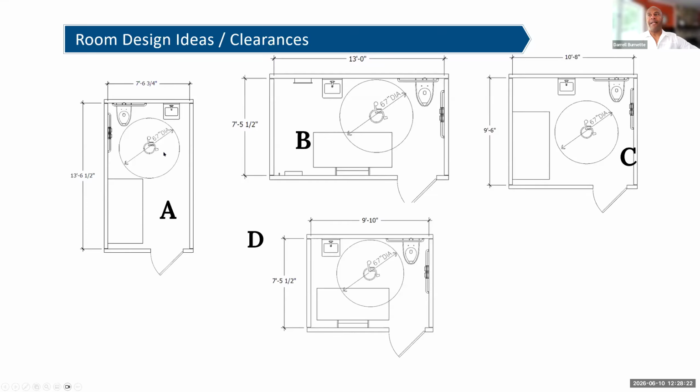be the minimum. And typically, when you're helping someone design the room, I get calls all the time saying, we've got approval for a table. We have no idea how we want it set up. So I close my eyes when I'm on the phone with them. I'll say, okay, I'm walking in the room. I'm walking in the door. Where's the toilet? Where's the sink? Typically, in the US, in a public restroom, the toilet has to be in the corner. It will be in a corner 9 times out of 10. The sink will be on the same wall as the toilet because of the water supply, 9 times out of 10. Maybe not exactly the same, but it's going to be somewhere in the vicinity.